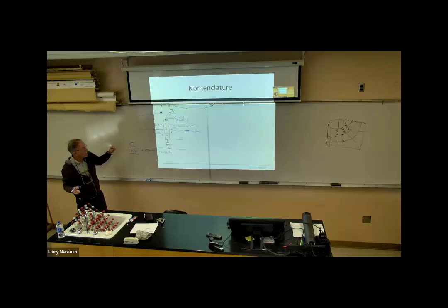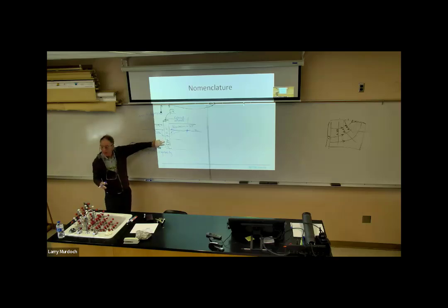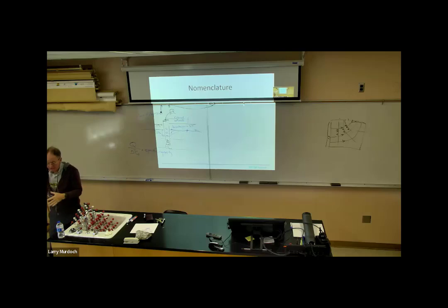So that's going to be important because there's a pump down here. And this is the drawdown in the well. You know, if the drawdown in the well gets to here, the pump doesn't have any water to pump. And a lot of times the pumps that we use are electrical centrifugal pumps. They spin around real fast with an electric motor, and if they don't have water coming into them, that motor doesn't get cooled and they burn up.